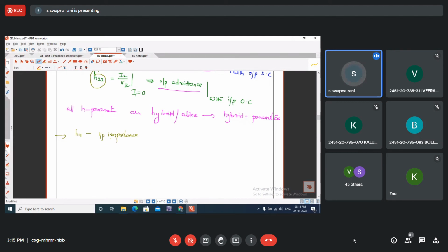So H11, and I will write it one more time for your sake. I will write the second equation because I know very well that output current IC is a function of input current and output voltage, right? So H21 I1 plus H22 V2.